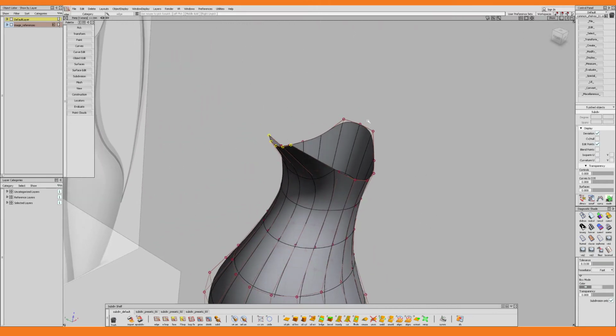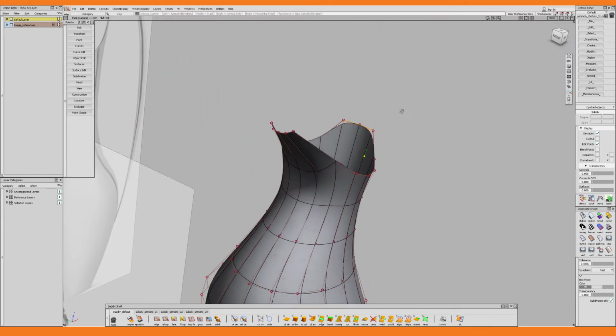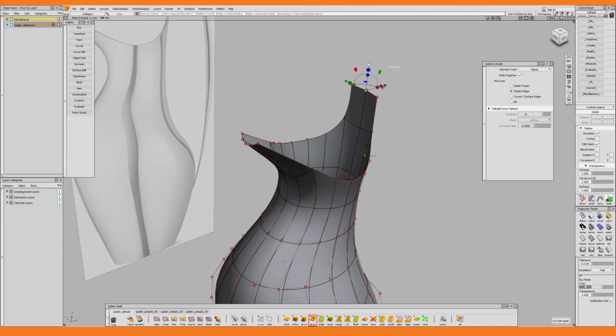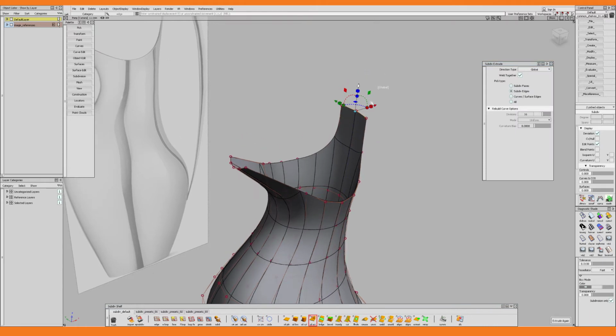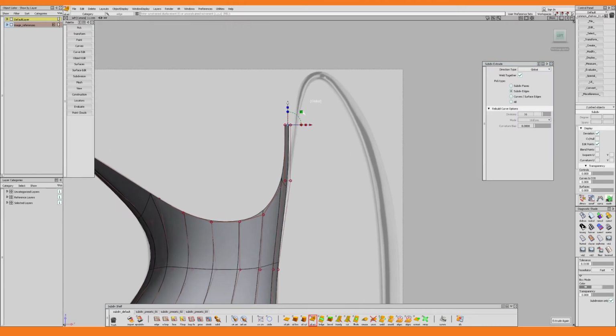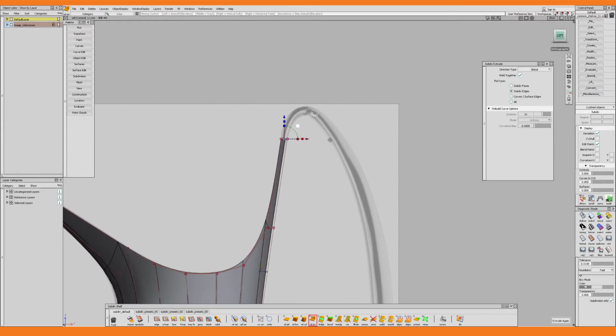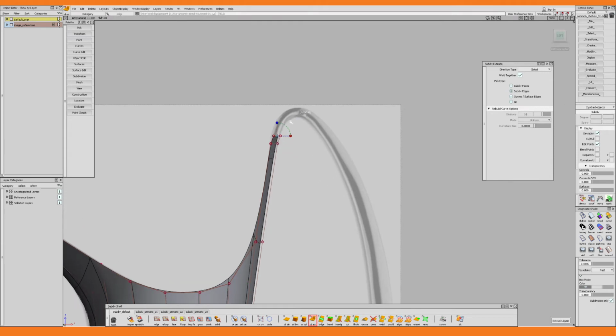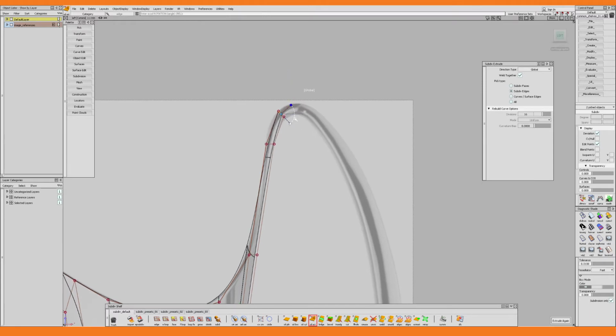I'm happy with the way the beak looks for now, so I want to create the extrusion for the handle, while I'm selecting these 2 edges. And I simply make use of the Extrude tool once again. I pull the blue arrow, and then I go into the side view. Here I move everything into place. And then I continue to make extrusions by clicking this Extrude Again button. Or I can simply press the spacebar and it will make another extrusion for me.